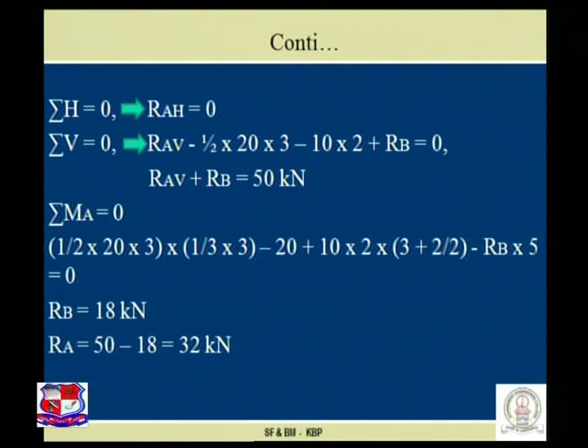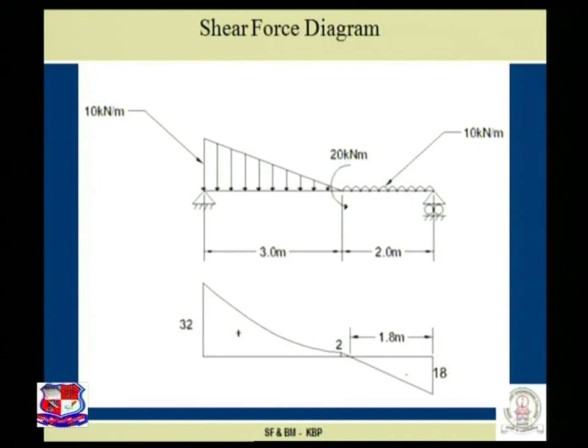So, using the three equilibrium conditions, it is very easy for us to find the support reactions. The next step is plotting the shear force diagram. Now let us plot the variation of shear force along the length of the beam.